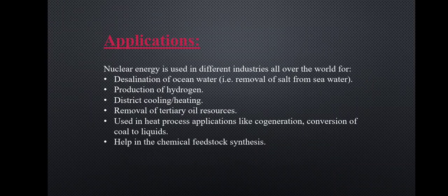Then let's see corrective maintenance. Corrective maintenance is further classified into two types. One is run to failure and the second one is unplanned failure. In run to failure, temporary repair, overhaul, refurbishment, replacement or modification are included. And in unplanned failure, inspection and failure diagnosis are included.